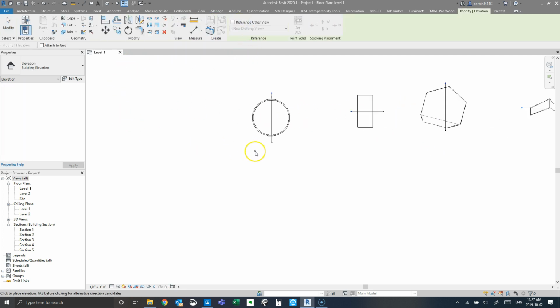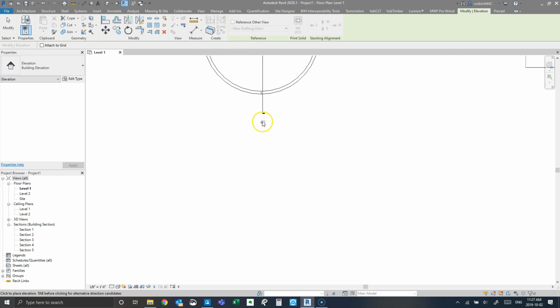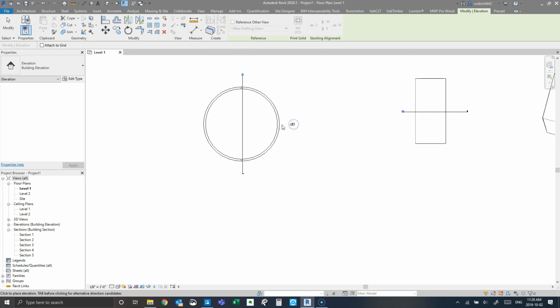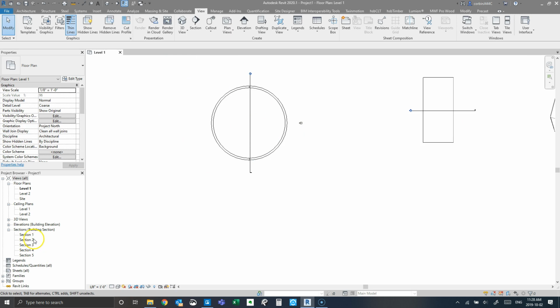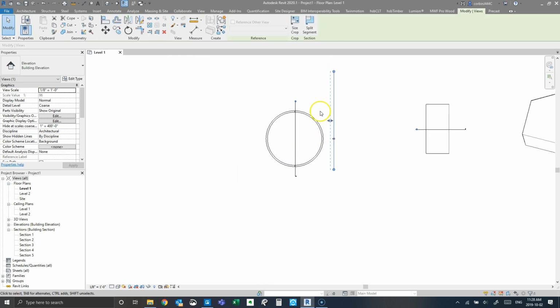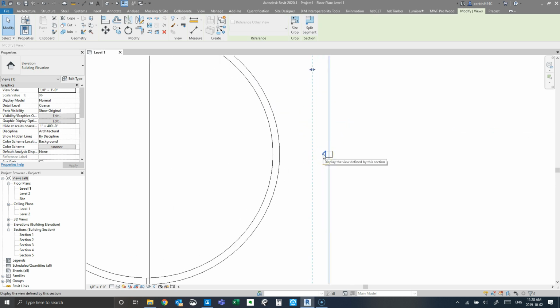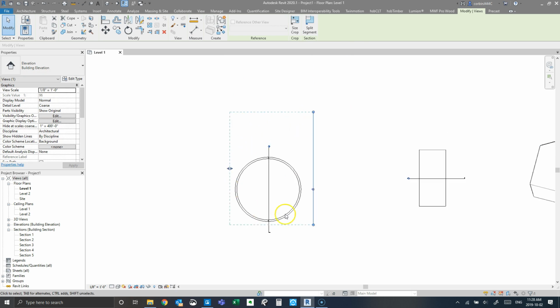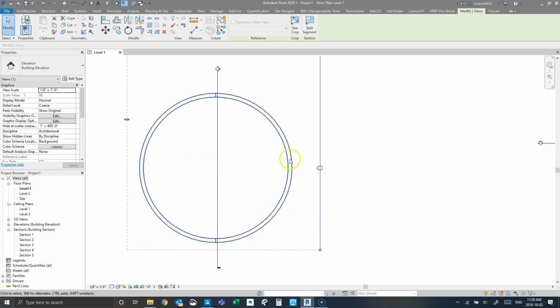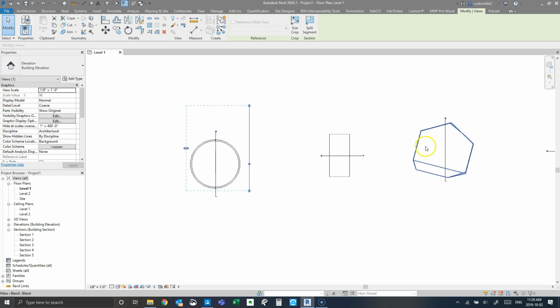you that we're going to also do an elevation. And we're just going to place the elevation right here. And the same thing we're going to do, just make sure we keep the same order going across so that all our views and our sections are oriented in the right direction. For the elevation, we just want to make sure we click this head here and bring this view extents line down so that we're actually seeing the whole building. If any of you haven't been able to see your actual full object, that could be why in the elevation. So I'm just going to go ahead and create the rest of these elevations across here.